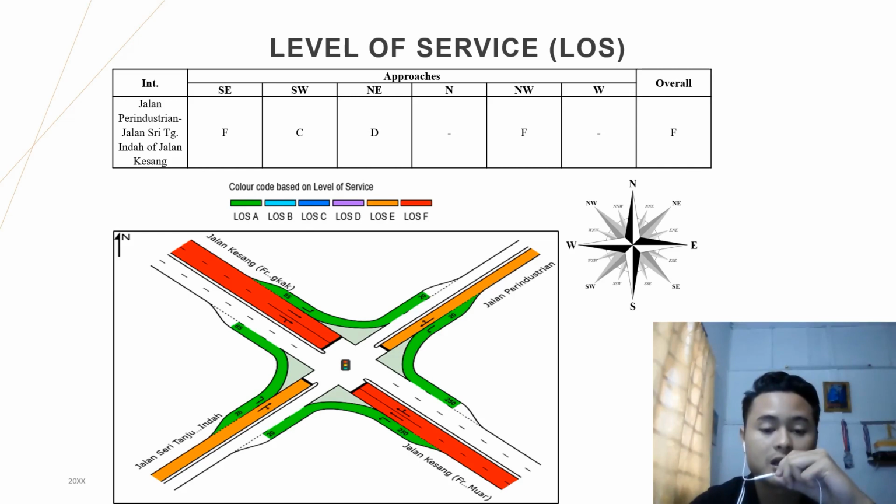So based on the performance results, the key indicators of the performance of the signalized intersection are, first, high traffic volume during the evening peak hour causes inefficient use of road space and congestion in the traffic flow. The second one is the traffic signal system's poor timing that increases the length of the vehicle queue.